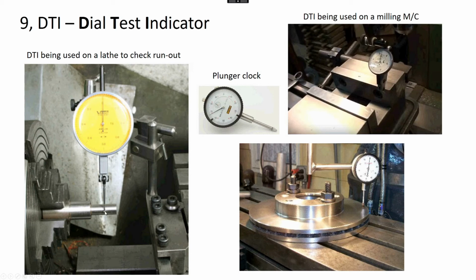If it's single run out, it would be done on this location. You'd spin it through 360 degrees and you measure the run out. Then you take the clock off, you move it to here, and you measure the run out here. Take the clock off, measure the run out here. But the run outs here, here, and here, if it's a single run out, aren't linked. They're treated independently. If it's a total run out, you guide the clock across the surface, and it's all one zone.